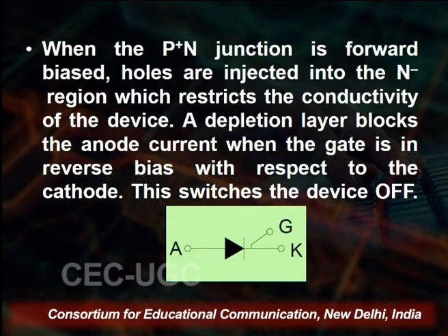In the case of the static induction thyristor, which is also known as the field controlled diode, it allows the conduction of large current with a low forward voltage and turns off quickly, and it is a high frequency power semiconductor device. This device is in the on state if the anode is positive and gate voltage is 0. This makes the device behave like a diode where the current is allowed to flow free from any obstacle. Now, you see on the screen, this is the diagram of this type of thyristor. Now there is more we will discuss in the further lectures.